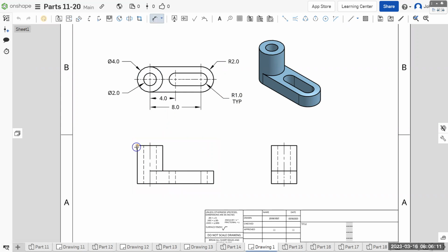And then total width is also not needed because we have our distance in the middle, plus we know this is 2 more inches, and here we have 2 more inches. So we know it's 8 plus 2 plus 2. We don't need that 12. So that's it for width. We don't have any other widths.